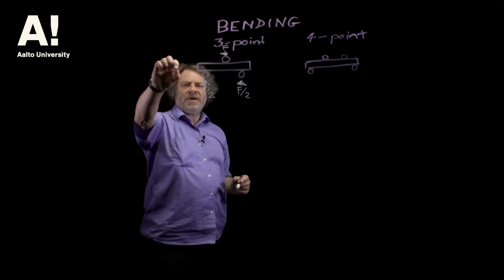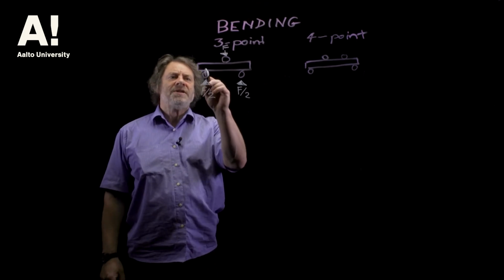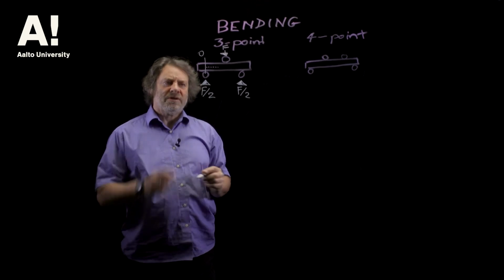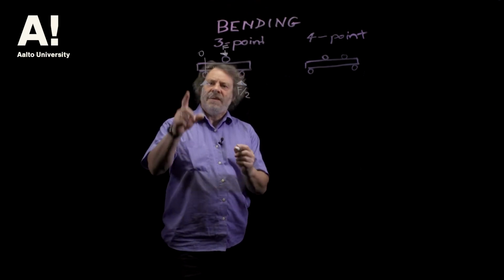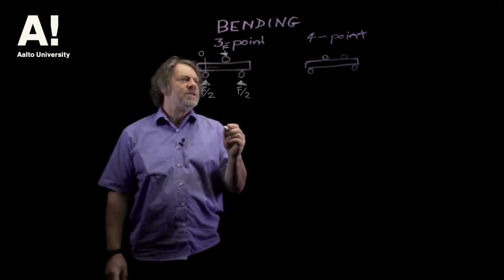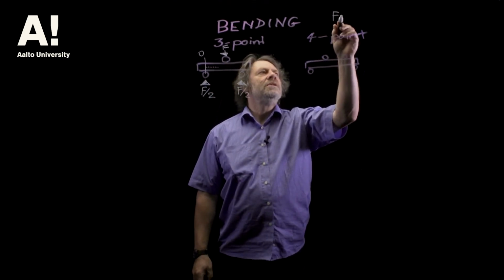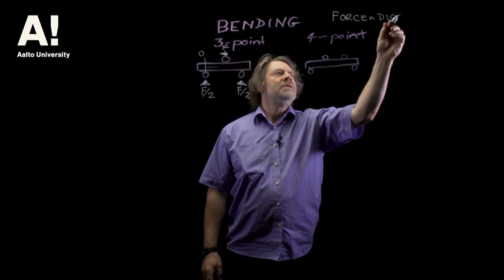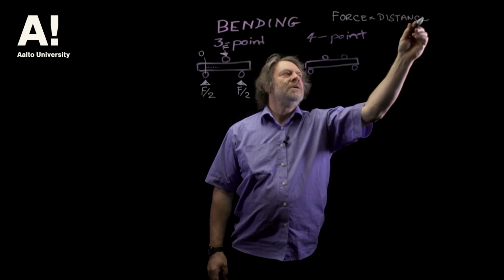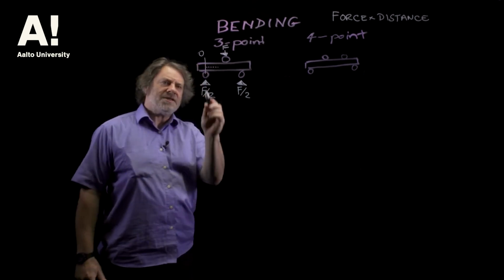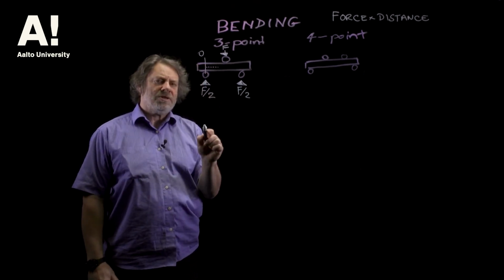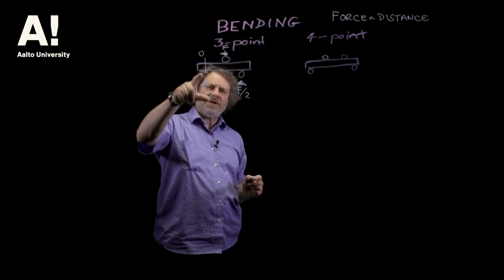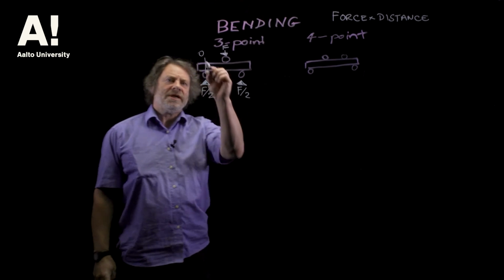So we treat this as a beam that's supported at one end, and we basically start here at point 0 and we move across and we analyse the forces that are applying. And remember that a moment is force times distance. So what force is being applied here is an upward force at point 0, but obviously it's going to be a bending moment of 0 because we're at length 0.